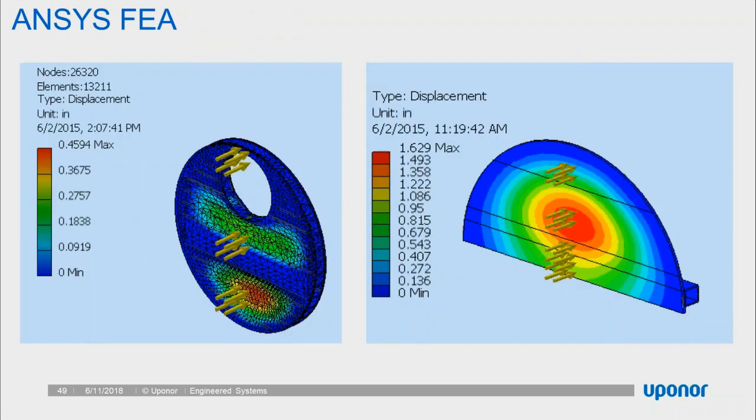Similarly, for bulkheads and other elements that require reinforcement or steel to be placed in the angular profile to support the loading, we run an ANSYS FEA analysis to determine deflection, apply reinforcement, and rerun it until our deflection is within allowable tolerances, typically 3% or so.